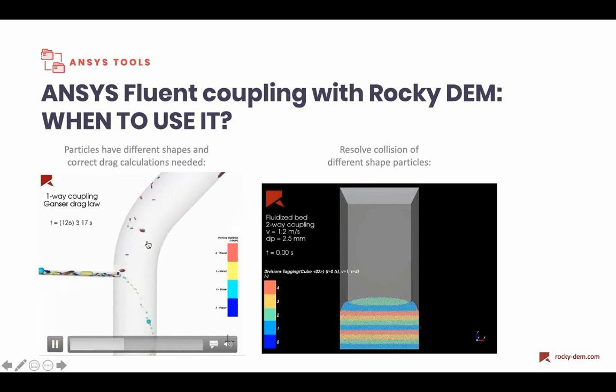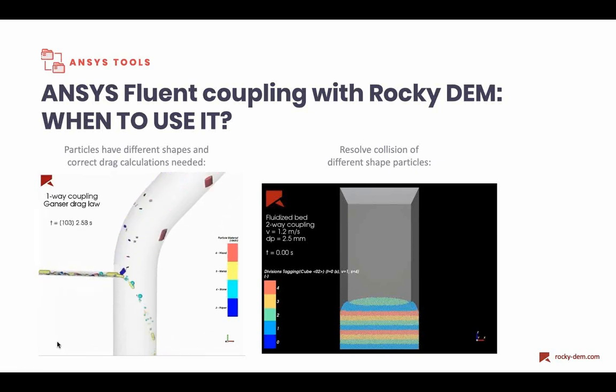The difference between the lift and the drag and the weight of the particle dictates which particle should move up and which particle should move down. For example here, you can see that the brown ones and the blue ones, with more surface that sees the fluid flow, are the ones that are moving up. So you can compute here, for example, the separation efficiency.